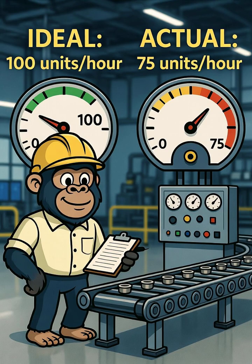Here's the key difference between availability and performance. With availability, the machine is completely stopped. With performance, the machine is running, it's just not running as fast as it should be. Both cost you money, but performance losses are often invisible unless you're actively measuring.